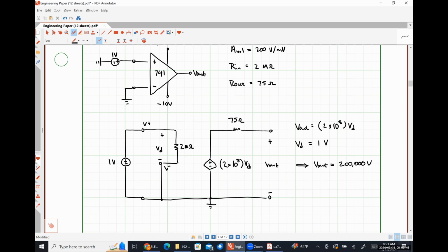No. Okay. These aren't magic devices that allow us to generate incredibly large voltages by any stretch of the imagination. They have limitations. The limitation on the output voltage of an operational amplifier is, loosely speaking, whatever our supply voltages are.